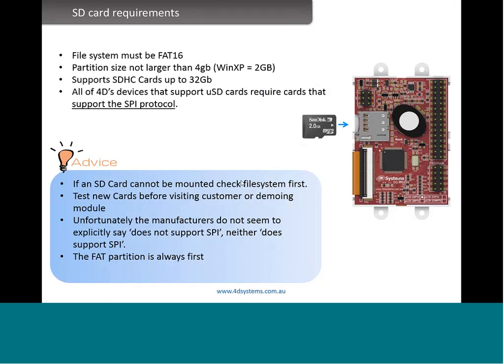So, the SD card requirements. This is actually a topic which comes up very often. For 4D Systems display modules, or basically all 4D products which use SD cards, the file system must be FAT16. FAT16 has limitations in the file system itself. It's not a 4D thing.